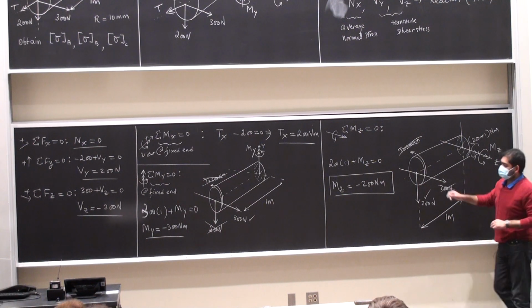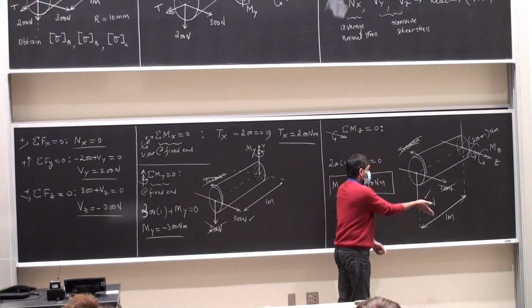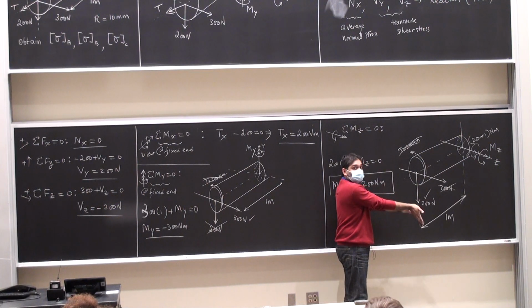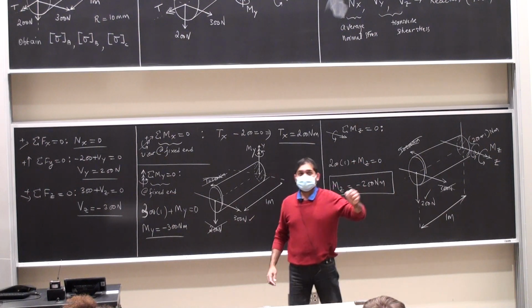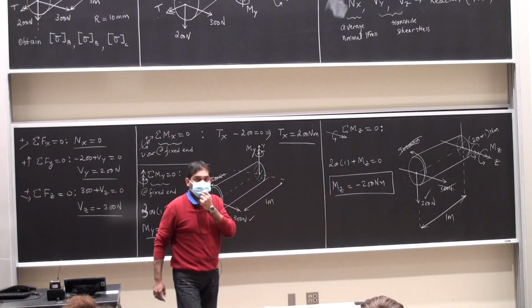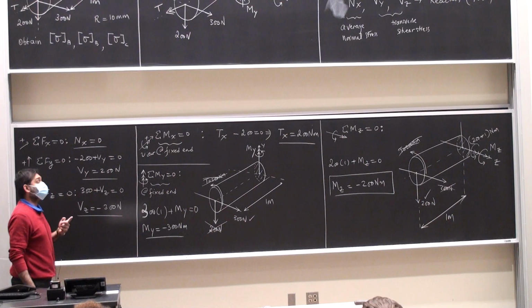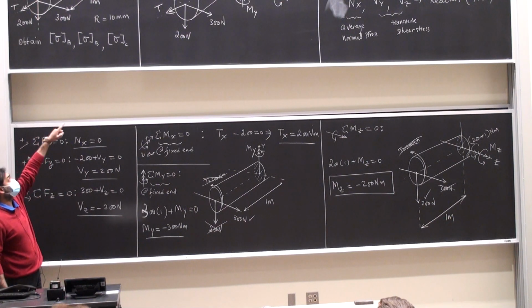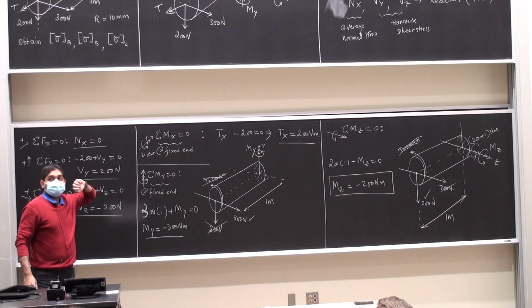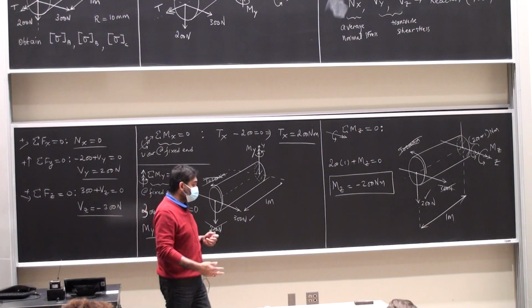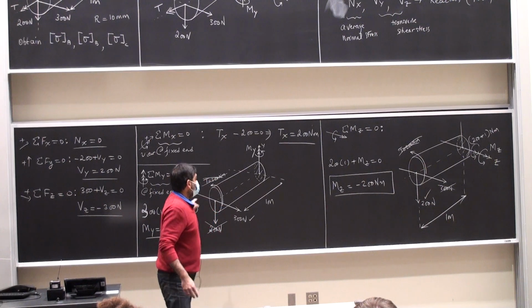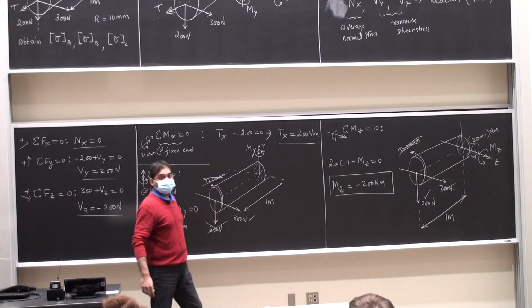Yeah. And right hand rule for this 200 newtons: fingers align with the force, my palm faces the z-axis, curl my fingers. It comes out of the page, which is my positive z-axis. And all this is based on the axis system that we created together. I could label these axes as completely different, choose two directions, and call the third direction using the right hand rule. The subscript should be changing on each of them.